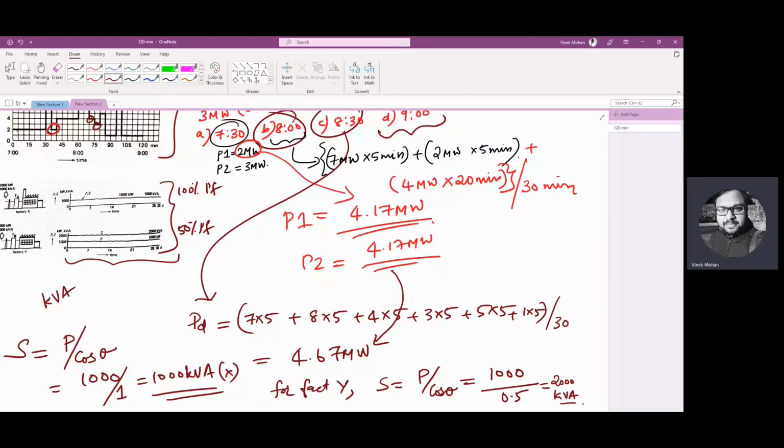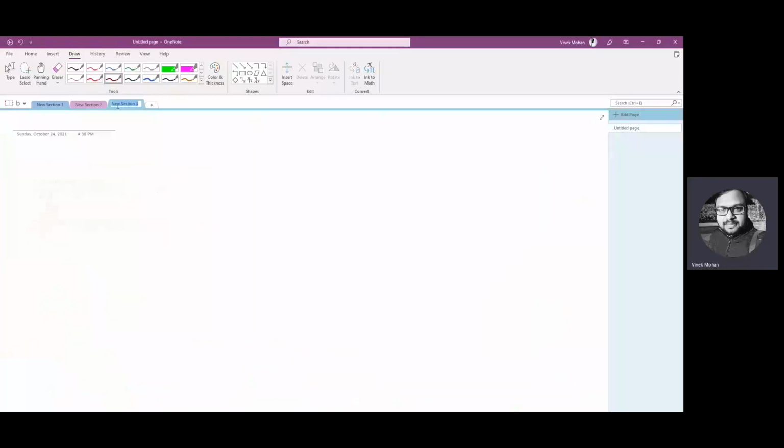So you can see here the 1000 kilowatts is same, both demand and energy are same, but because of the power factor, this comes into picture. The problem is with kVA that reflects on the line current. So that is what we have understood from this particular example, the importance of charging in kVA terms for industries.